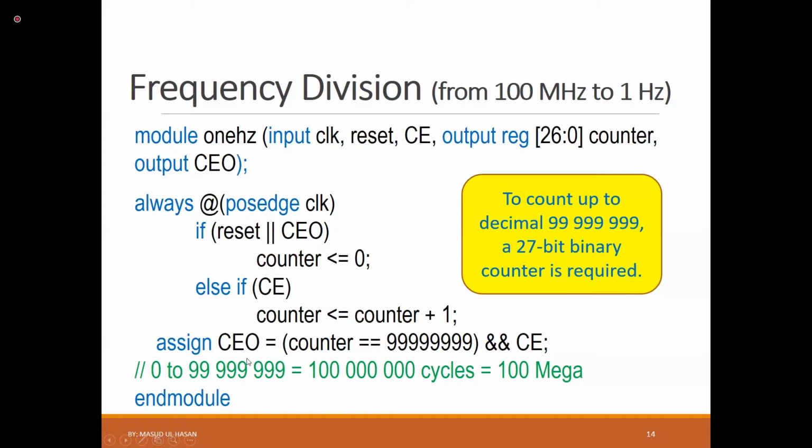See, if everybody is listening, I will explain it again. I explained it last time also. 7 segment display is what? It is an output. And you know that for any input or output, we need a UCF file. For 7 segment display, you don't know what are the names of those segments and the anodes. Remember, there are 2 outputs, segment and anode, for 7 segment display. So you don't know the names. So we put this in the UCF file of 7-segment display. When you add source this V file of 7-segment, you have to add source the UCF of 7-segment also.